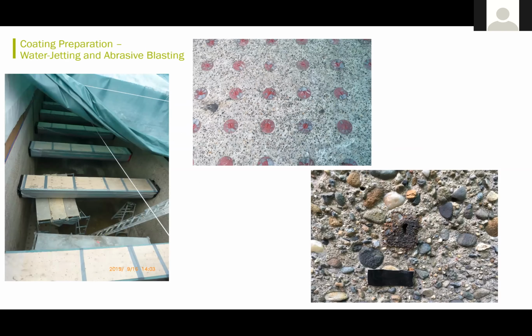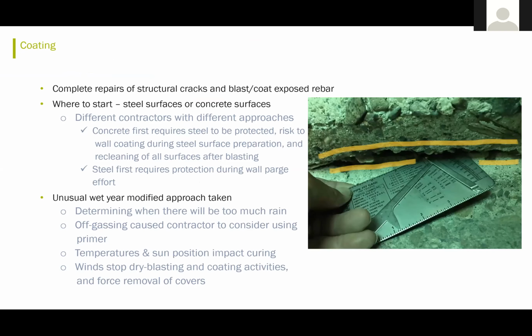Just a couple shots that were taken. One in the center is the floor area where they removed the nozzles and installed temporary caps before they blasted. After they finished with blasting, they repaired the structural cracks and coated the exposed rebar.